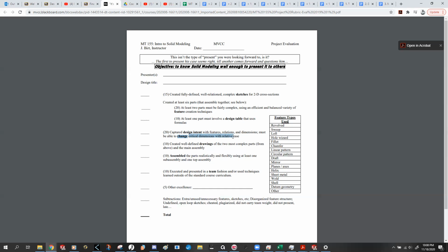So I should be able to make it longer, shorter, wider, narrower, more open, more closed, whatever, in various key dimensions. Okay, I'm not talking necessarily about a fillet, because fillets can break pretty easily, but some of the bigger things. If I were to make a family of these parts, would I want them to be longer, shorter, or deeper, or what? Thicker, thinner? Make sure that those things can be changed, not for any value, but within a reasonable 10, 20, 30, 40, 50% range.